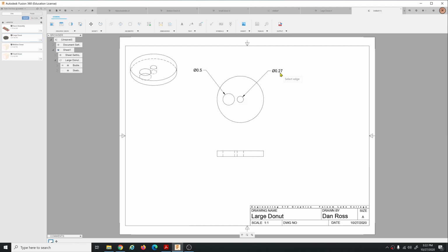So there's 20 thousandths or 0.020 clearance between the shaft and the hole, right? If you 3D printed this or made it by any manufacturing process, it's been my experience that 20 thousandths seems to be a good clearance for most 3D printers for this kind of design.